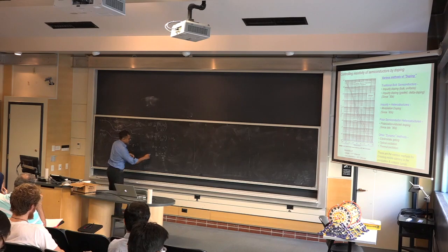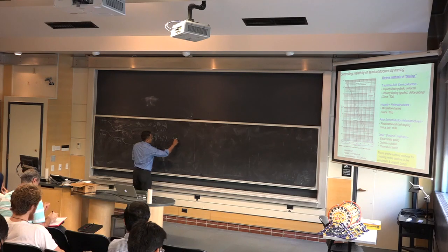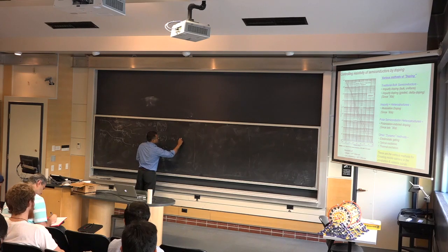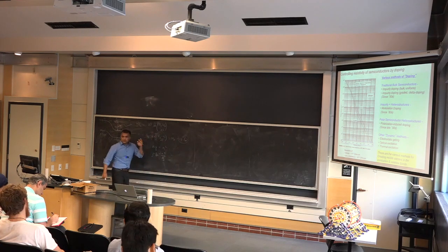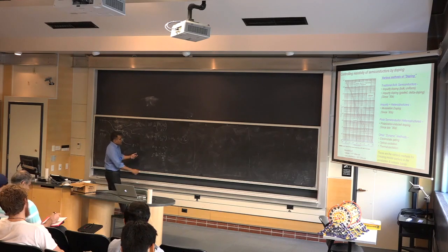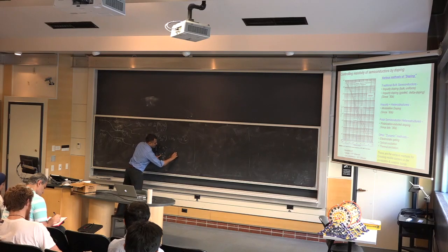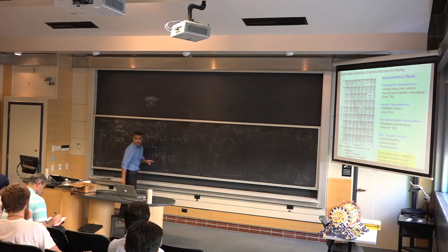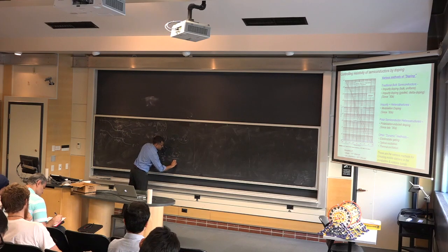And as a result of this, let's look at some of the numbers. For example, let's say I have doped silicon at 10 to the power 17 per centimeter cube. Then I know that Ni for silicon is 10 to the power 10, right? That we discussed or derived in the last class. So 10 to the power 10 squared over 10 to the power 17.